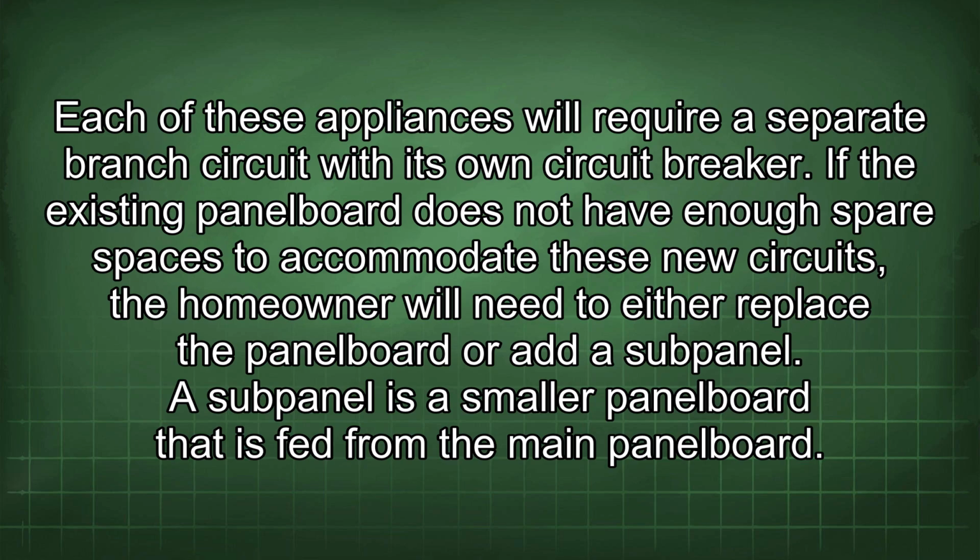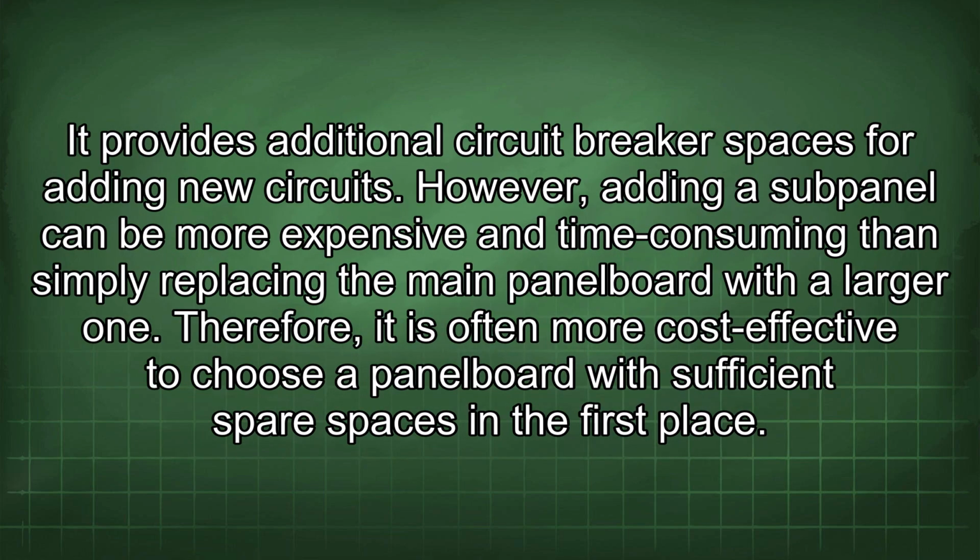A subpanel is a smaller panel board that is fed from the main panel board. It provides additional circuit breaker spaces for adding new circuits. However, adding a subpanel can be more expensive and time-consuming than simply replacing the main panel board with a larger one. Therefore, it is often more cost-effective to choose a panel board with sufficient spare spaces in the first place.